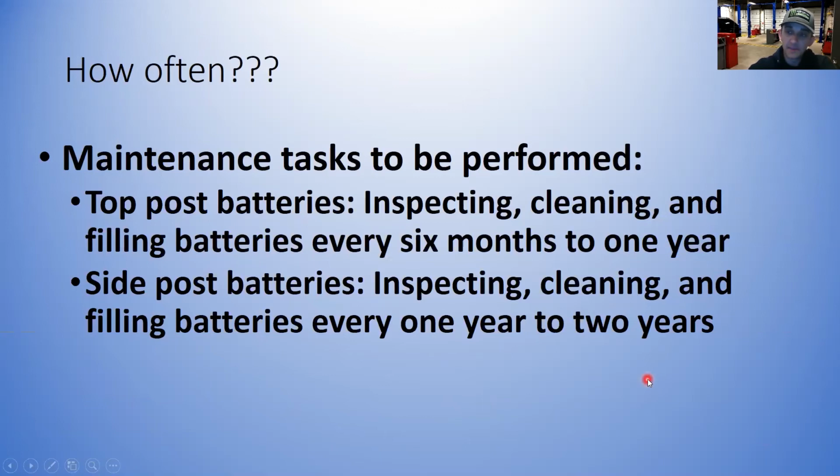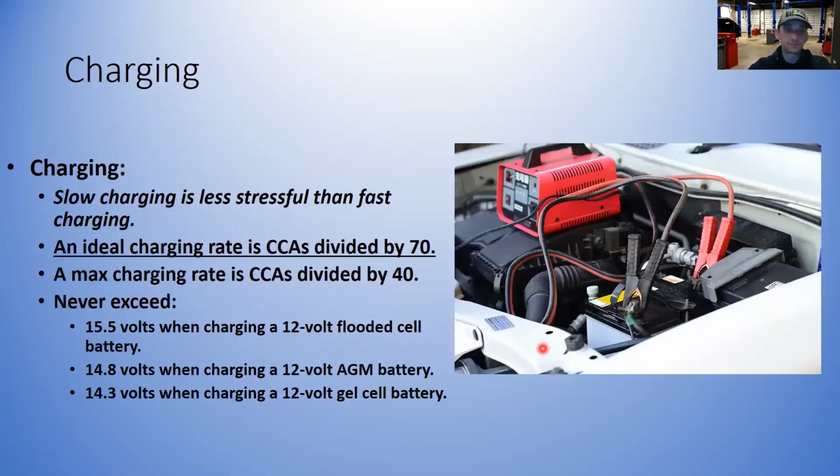Because side posts have a better seal, a little more of an airtight seal between the cable and the terminal. So there's a little bit less chance of corrosion and oxidation building up on there. So that's why they extend that a little bit.